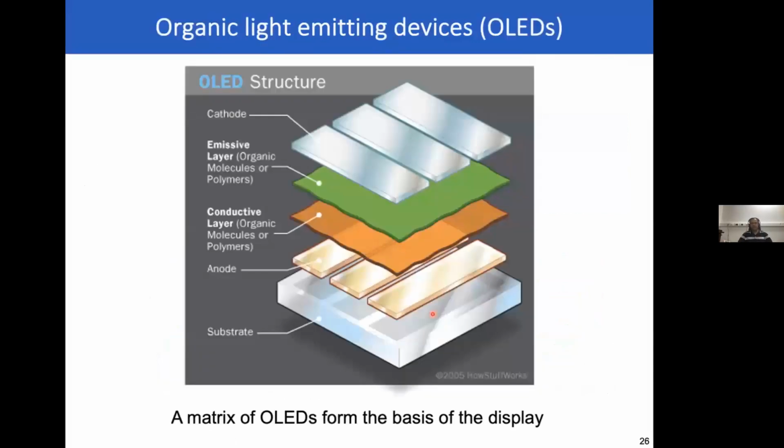The next thing we're interested in is, of course, can we actually use nanowires for a display? Silver nanowires can't be the active layer for any display because typically these are some sort of semiconductors. And of course, the most common structure is an organic LED structure, which is a multi-layer structure having an emissive and a conducting layer. Typically, these are organic polymers. But we are interested in low power, low cost displays that can be used for signages or interactive posters, where essentially OLEDs are too expensive and are not used.